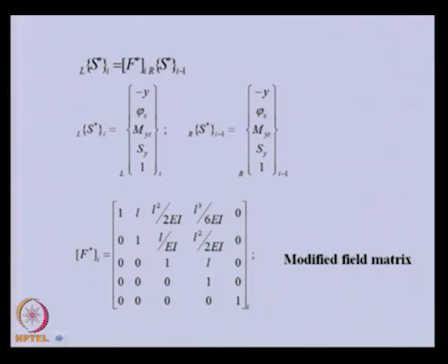If we have external force, then as we did in the torsional vibration case, we need to modify this field matrix by adding one identity at the lower position. So basically we are adding 1 equal to 1. You can see this field matrix is added with all 0 except the diagonal term, and here also 0. So again if we substitute this and this state vector here, and expand the last equation, we will get this.